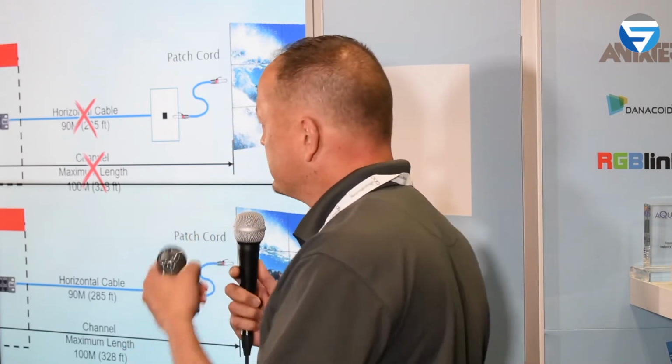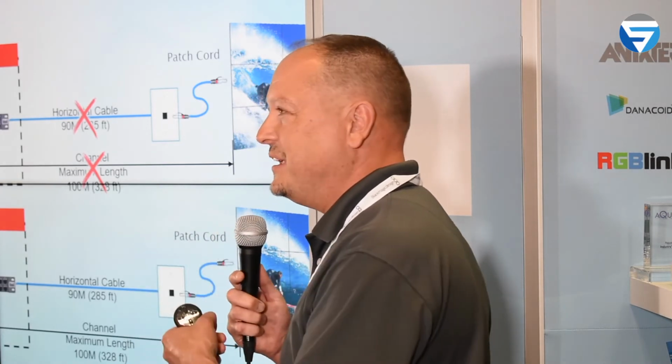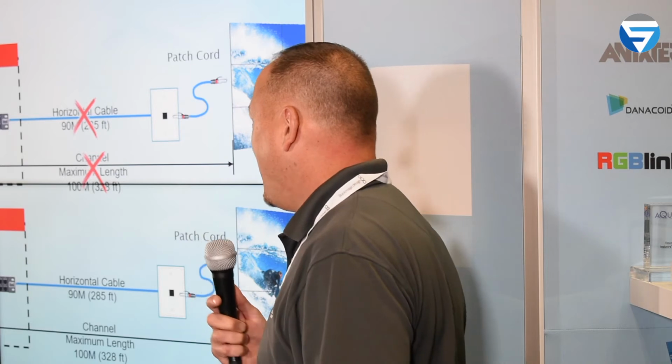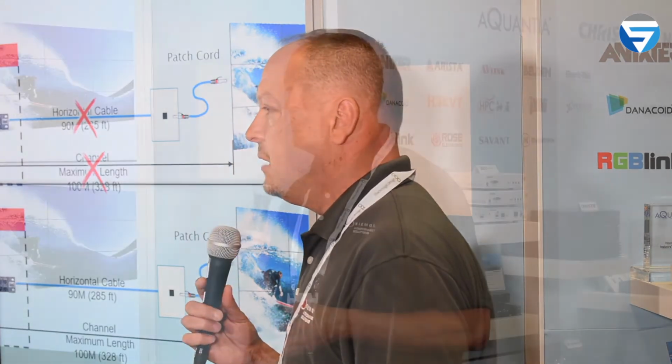I've talked to installers who show up on the job with Category 6A and Category 6 cable. In this configuration, they'll try to run the Cat 6A cable, and if they don't get video, they'll put in the Category 6 and give that a try. I think it's kind of hilarious how some of these approaches are, because there are other ways around just plugging in the devices to see if you're going to get video or not. There's a whole testing procedure that can be gone through, and it takes the guesswork out of the whole equation.